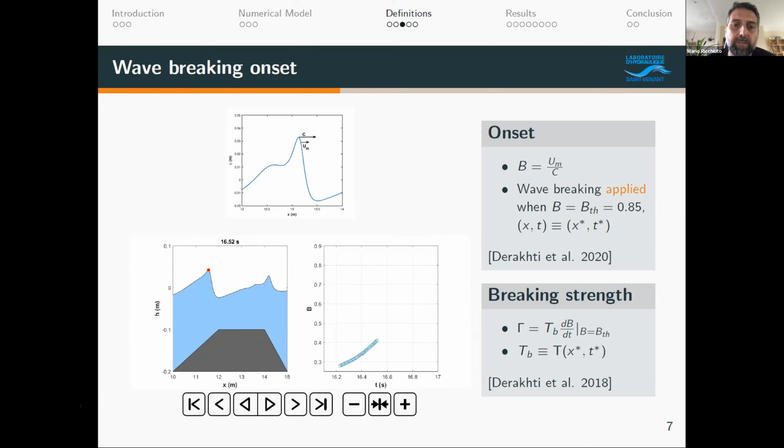Okay, fine. Can I make a comment? Actually, the velocity in the B coefficient is not the phase speed, but the crest speed. In an unsteady wave, the crest speed is different from the phase speed. I understand that your implementation is practical to get an estimate, but ideally you should track the crest location and then estimate the crest speed. But I guess that would be very numerically challenging. It would slow down everything.